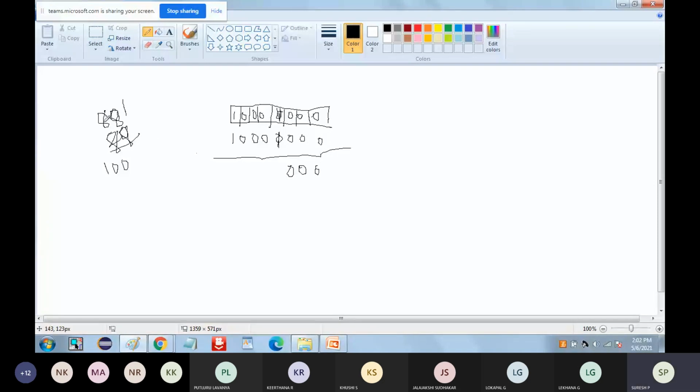So first I will take 0808, then you will understand clearly. If I take 0808, what will happen? The carry is generating from here. 1 plus 1 is 0, but carry is generated to the 5th bit, so it will be 1. Now, for this type of operation, your carry flag will be 0 only. Why? Because the carry is not generated from bit number 8.